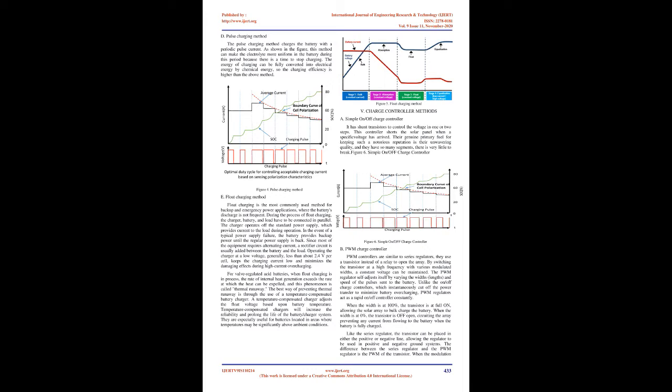When recharging a NiCd battery that is not fully discharged, it remembers the old charge and continues there the next time it is used. The memory effect is caused by the crystallization of the battery's substances and can permanently reduce your battery's lifetime and make it useless. To avoid it, you should completely discharge the battery and then fully recharge it again at least once every few weeks. As this battery contains cadmium, a toxic material, it should always be recycled or disposed of properly.